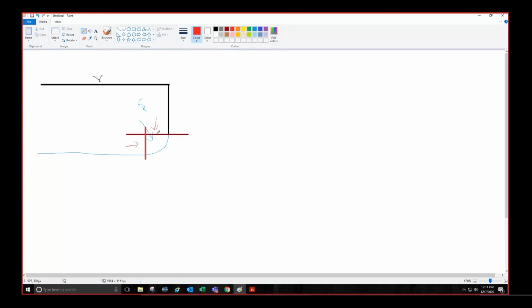So we can resolve this resultant force into two components. So what we do is redraw this curved body like this, and we have these two projections here. Sorry for the bad drawing. So we redraw this curved body and we project its rectangular surface like this. So there will be a force on this top projected area, which we label as F2, and we label this as F1.